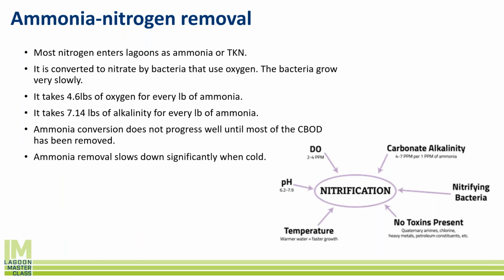4 degrees Celsius, 39 degrees Fahrenheit is sort of the coldest your water will get in a lagoon and stay liquid. That's going to be on the bottom of your lagoon. You're going to be at about half the pace or slower at that particular temperature. You can nitrify all the way down to just above freezing, but it goes very, very slow.